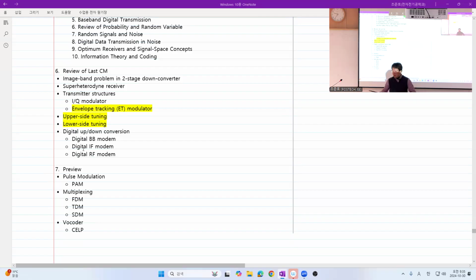So it's like, given the IQ modulator formula, which is simply the representation motivated by the representation of a real valued bandpass signal as a sum of the in-phase component plus the quadrature component, right? And from that equation, it seems we need a perfectly coherent, phase coherent cosine function and sine function. However, he considered, why not use two stages to upconvert the signal?